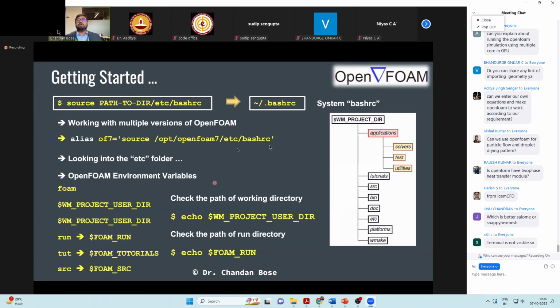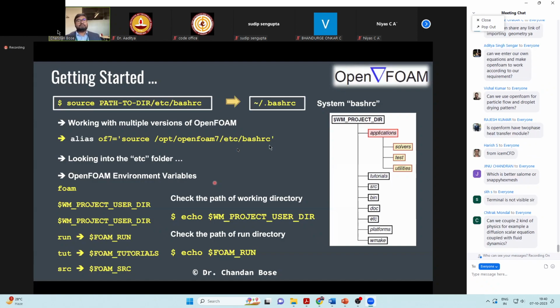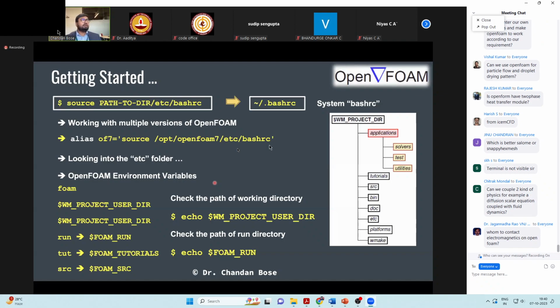So once you get the computational results, to believe it, to know that they are accurate, you need a very rigorous validation with respect to either other references in a statistical sense or with some experiments. Now, Salome, I would really suggest you to learn GMSH and Salome to actually start learning how to make better meshes.